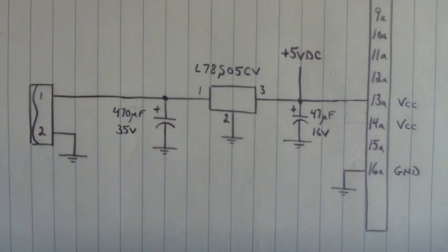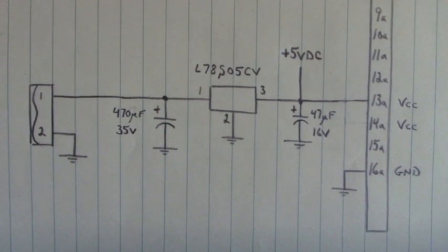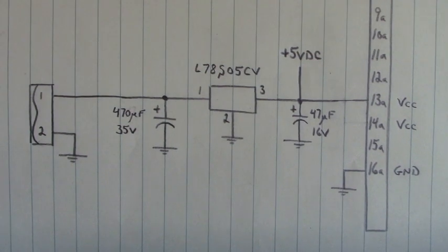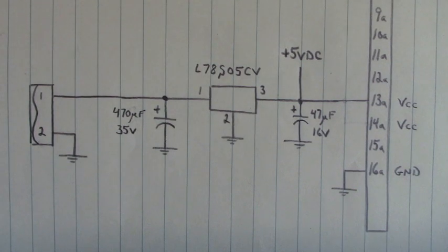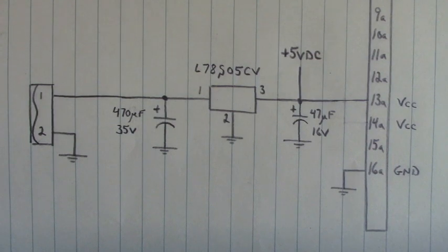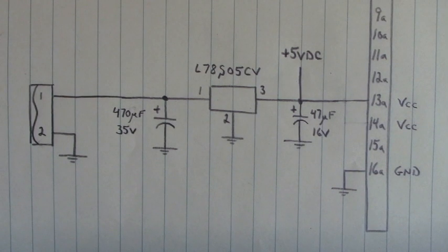So this is why we have to power up that Indramat software module with our own power supply, and don't even use the one from the programmer. Use this one. Don't connect pin 28 of the programmer to pin 28 of the EEPROM. That's what I'm trying to say. It won't work.